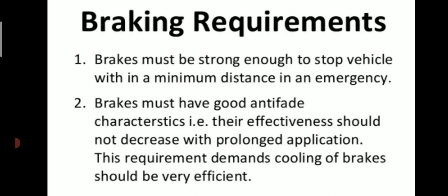Let us see what are the requirements of braking. Number 1, brakes must be strong enough to stop the vehicle within a minimum distance in an emergency. And number 2, brakes must have good anti-fade characteristics. That is, their effectiveness should not decrease with prolonged application. This requirement demands cooling of the brakes, and it should be very efficient.